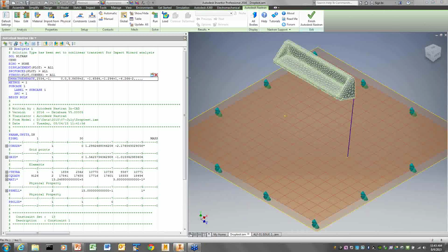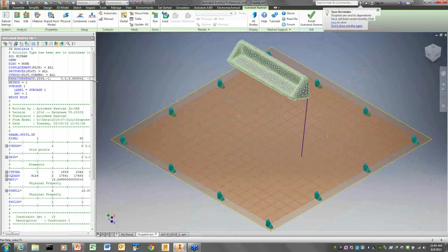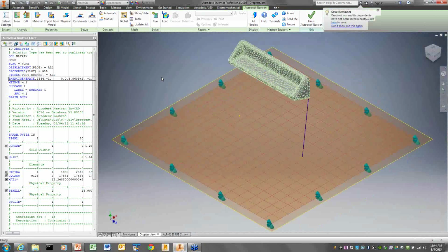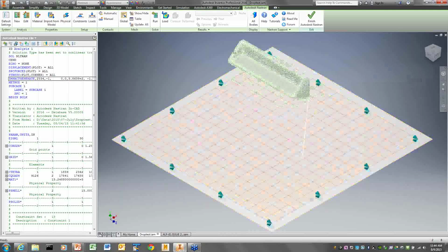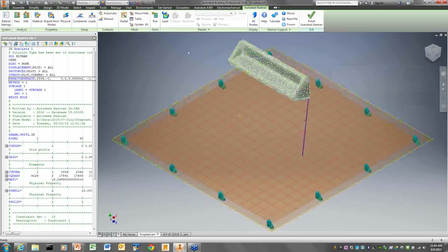I understand. Which then leads you to why use the automatic, use the manual at that point. Yeah, at that point you're starting to think maybe I should be using the manual. Again, with the manual you have to pick the time steps and do sensible stuff and know the modal characteristics, but I might argue that if you don't know the modal characteristics in the first place, you probably shouldn't be doing a drop test. Which isn't to say that I actually did a modal analysis on this when I ran it, but that's just me.